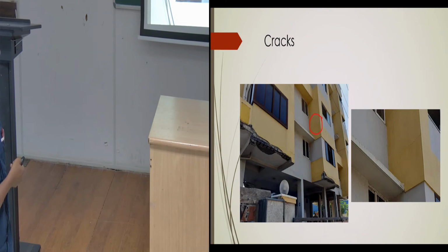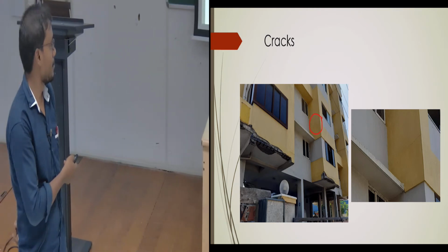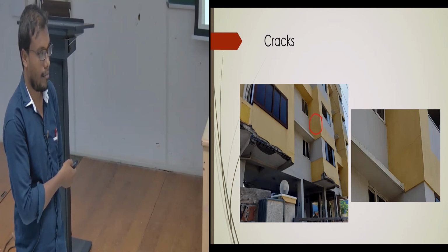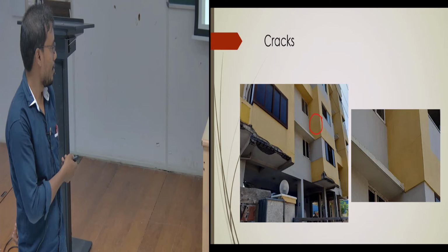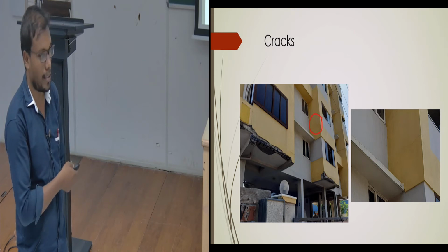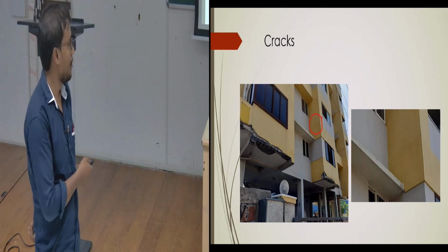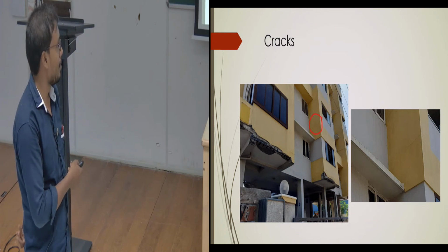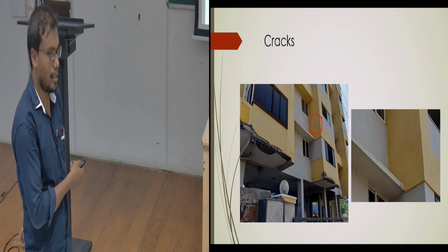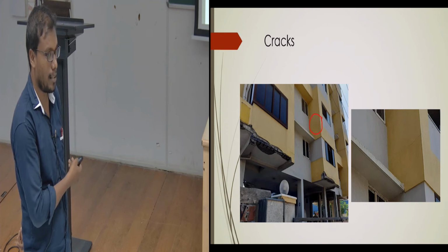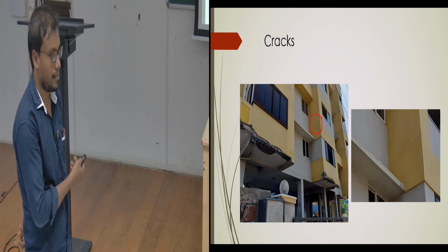I think if it has gone beyond 1 meter or 1.1 meter, this sort of problem would occur. Have you measured the length of that cantilever portion? Was it going beyond 1 meter? No, it looks like less than 1 meter. It should be more than 1 meter. That's why it is failing. It's a structural failure. There is no sufficient support. Much of a cantilever can be supported easily, up to 1 meter.